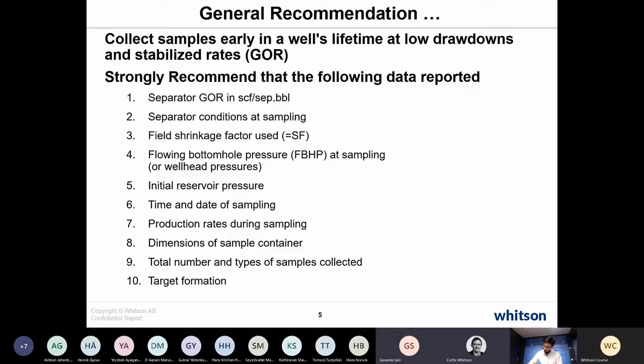There are, again, probably a limited number of EOS-based software packages that will model both the hydrates and the MEG. In this case, you're looking at the effect of MEG on the gas-oil phase behavior through contamination. Solubility of MEG in, let's call it the hydrocarbon phase or phases. I've only studied H2O directly and not these inhibitors like MEG.